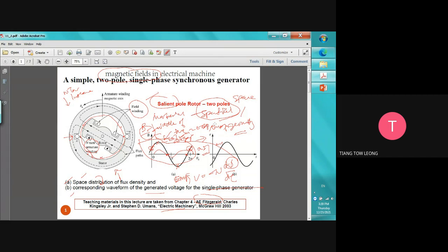Usually when we want to create a motor, we try to make the rotor and stator as close as they can be. For example, in an induction machine, the air gap between them is about 0.2 mm. You can use your ruler and have a look. How small is it? 0.2 mm. For permanent magnet, we usually put 1 mm. Okay? We will focus on the middle of the air gap, the magnetic flux density, so that we can know how good the EMF can be generated.